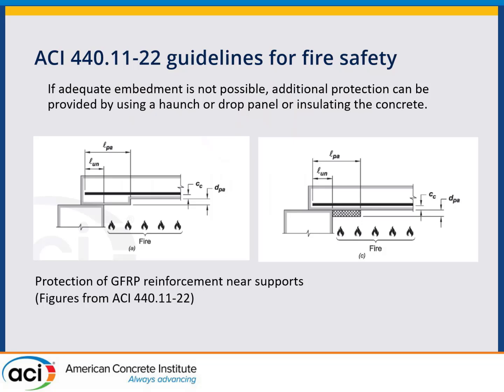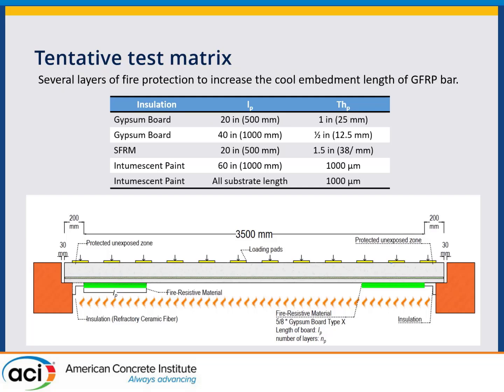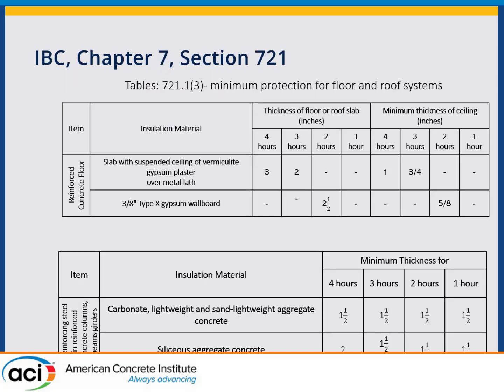So in those cases, you could perhaps look at some sort of protection from thickening the concrete or providing external insulation. And that's what some of this next work is, and I know Hamzy is really the one leading this part, looking at different types, using gypsum board for this insulation, or spray applied applications, and also looking at intumescent paints to see how we can better protect these end zones. And that was not meant to be a football reference.